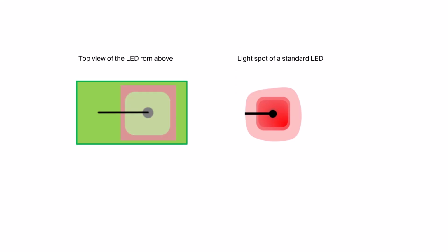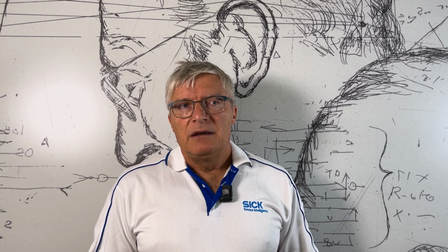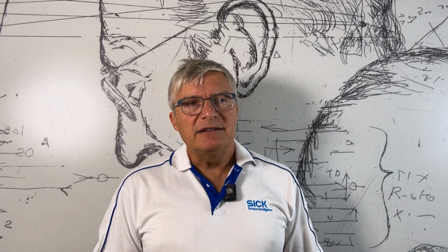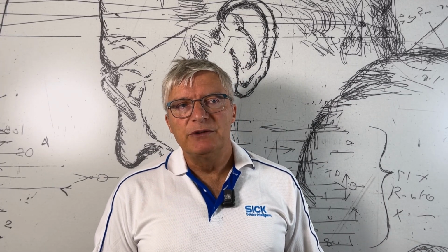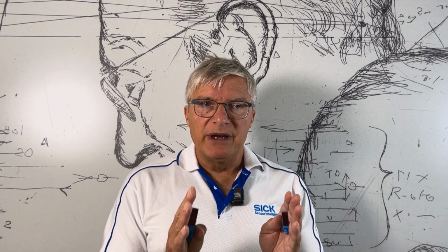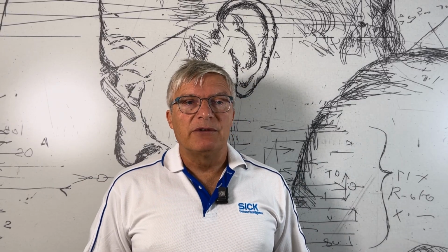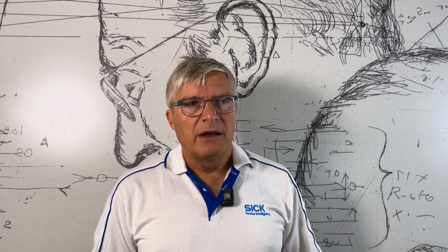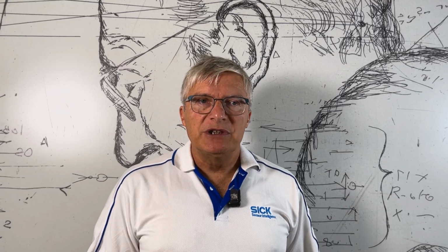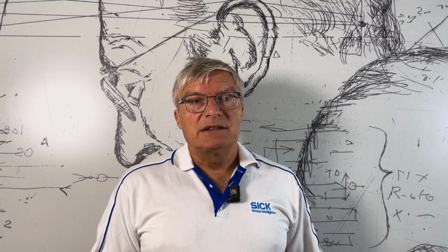This light emission results in a light spot and light beam that has gradations in light intensity, halo light, and a blind spot in the middle of the light spot. These properties, essentially the size of the light spot including halo light, have a negative influence on the precision of a diffuse background suppression, both in terms of the minimum distance of object to background and in terms of the influence of reflective and retroreflective backgrounds. The best examples are safety vests, which can still cause faulty switching in the background from many photoelectric sensors a few meters away.